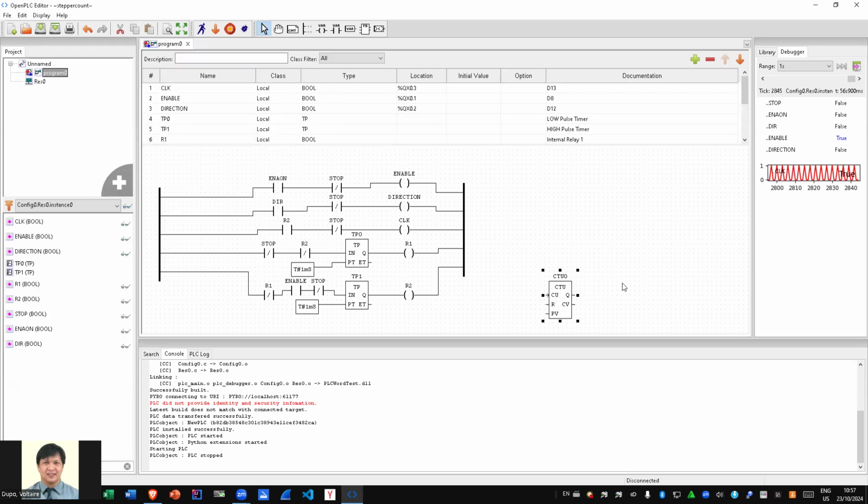Most counters will have this sort of action: count up or count down. In this case, we're just interested in a count up. The count up signal is the indicator that we're starting the count up function. The reset is for the counter to be reset, so we can restart the process.